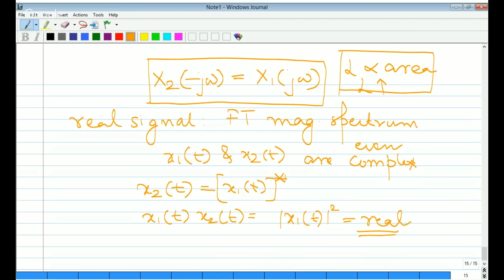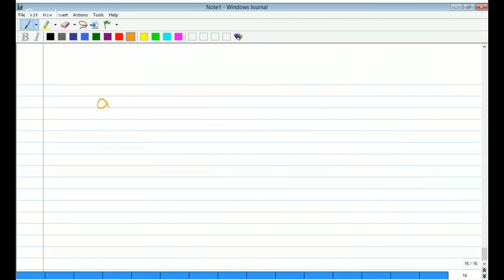Next question is from Soumya Ranjan Acharya. Explain about the ampere second balance of boost converter. It is clear about the inductor current, and in that, whether it is taken as instantaneous or average. See, one thing, when you are applying ampere second balance, IL will be equal to IL average.